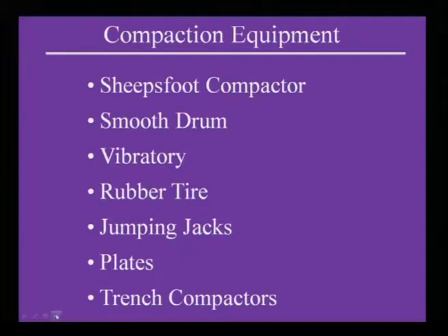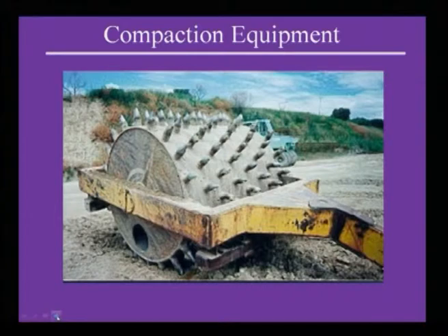Compaction equipment, if I classify it based on function: first is your sheep foot compactor, second is your smooth drum, third is your vibratory, fourth is your rubber tire, fifth is your jumping jacks, sixth is your plates, seventh is your trench compactors. Now, what is this? If you look here, this is your sheep foot.